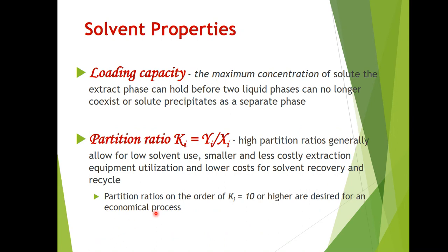Now we have also what we call the loading capacity. This is the maximum concentration of solute the extract phase can hold before the two phases can no longer coexist, or the solute precipitates out as a separate phase. The last phrase, where the solute precipitates as a separate phase, is already a case of crystallization.